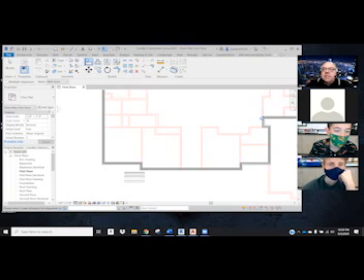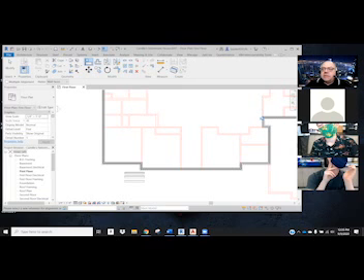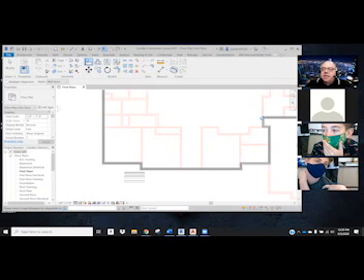The difference is in some cases, commercial buildings will use an aluminum stud, which has the same dimensions as the wood stud. You will also have a difference in your gypboard thickness. So Architecture 3 students, all of your gypsum board needs to be 5/8 inch thick, all of it, everywhere you put it. It's not a crucial thing to change in the model per se, but you want to go through and edit your walls so that all of the gypsum board is 5/8 inch thick.